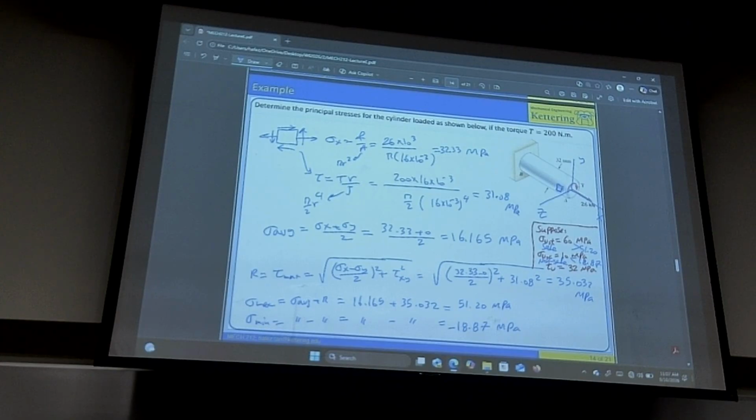Yes, Paul? Comparing tau u to tau max, 35 is over 32, so it's not safe. That means that all of it's not safe. Exactly. So remember, even though the load, the torque was this, we never thought that anything else would contribute to torque, right? But look at the equation. Max torque does get some contribution from sigma x. That's why we have slightly more than the input.